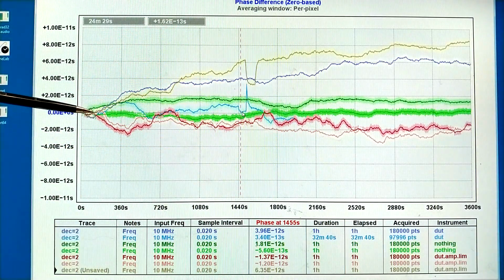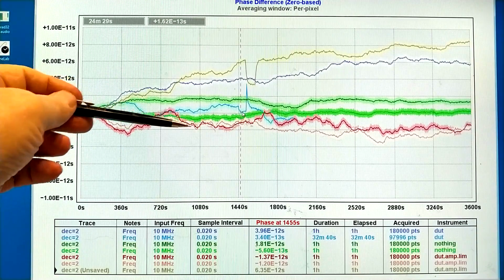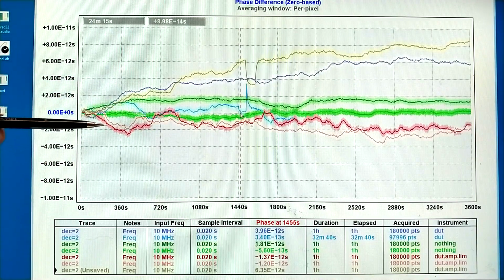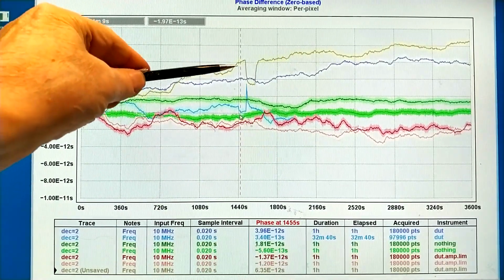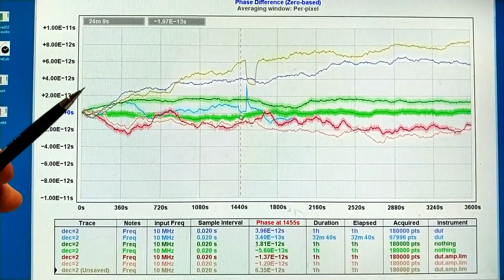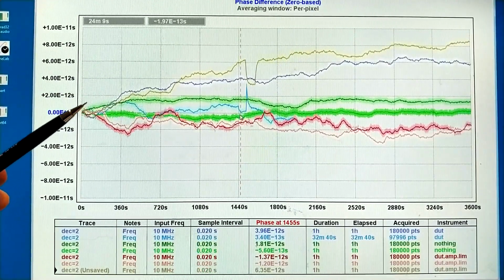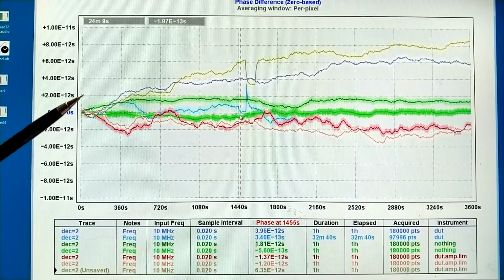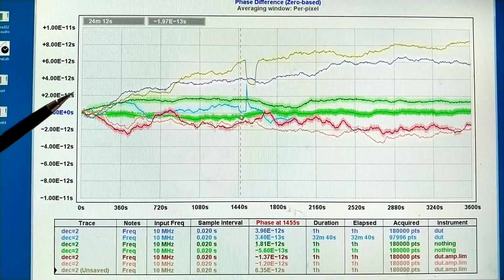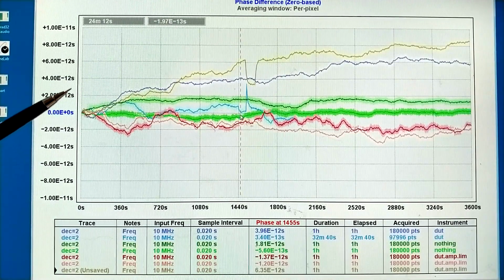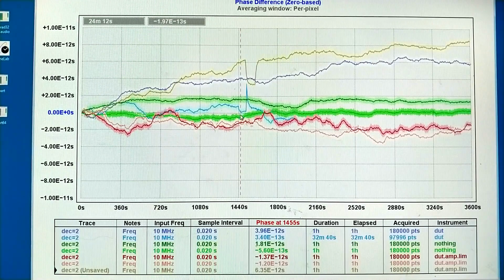And the temperature, I associate this with temperature changes, the slower, over hundreds of seconds. The noise here then corresponds to about 1 millivolt if it would be caused by voltage variations on the power supply. Now my DC voltmeter tells me that the power supply is more stable than that. So it is noise from the crystal or from the amplifier or from connectors or cables or something.